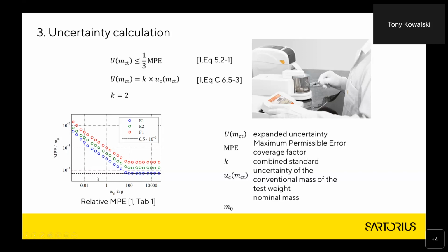So the uncertainty you'll find on the mass comparator is constant, and you'll see this value has less influence as we approach the maximum value of the comparator, because it's a fixed uncertainty. The smaller the weight that you're comparing, the larger the contribution this has to the uncertainty contribution from the weighing instrument.